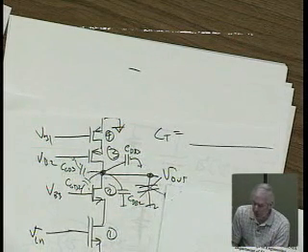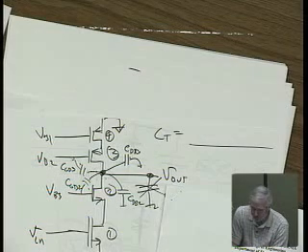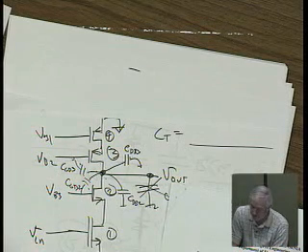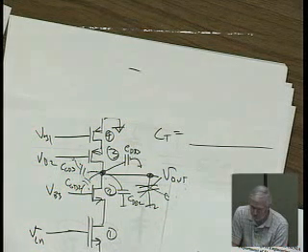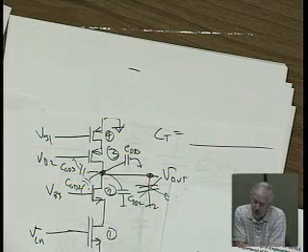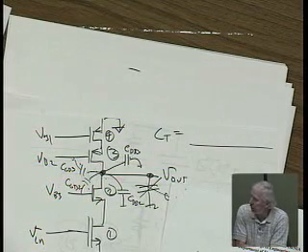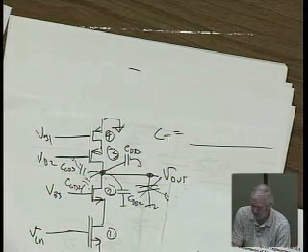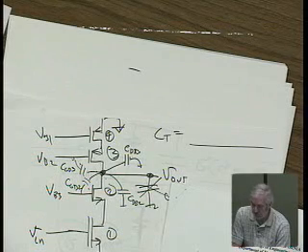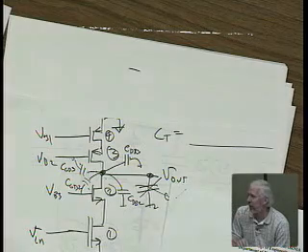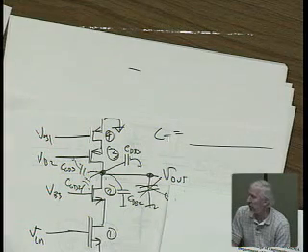Make sure you calculate the capacitors right, because we had very small values for the capacitors here, with just RO5 in parallel with RO4. The only thing I can say is to check the size of your capacitors and see how they compare to what Spice says. There are only two things that can be off, either the capacitors or the resistance. So check the R out of this thing. Is that the same as the R out that you get?